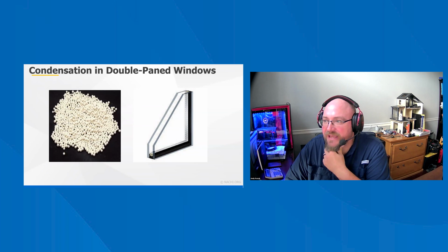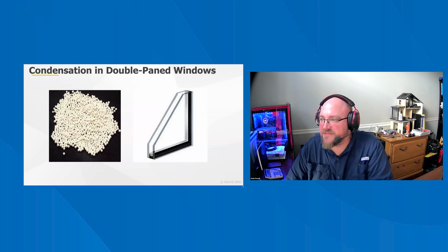Double pane windows have a layer of gas, usually argon or air, trapped between the two panes of glass and should be insulated enough to prevent the accumulation of condensation. If this type of window appears misty or foggy, it means that its seal has failed and the window no longer holds its insulation rating. A desiccant is an absorptive material designed to maintain dryness within its vicinity.